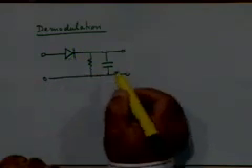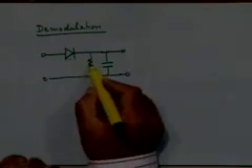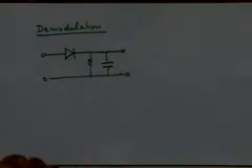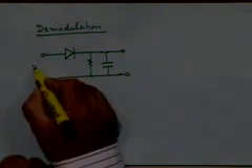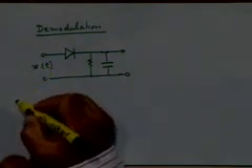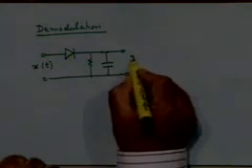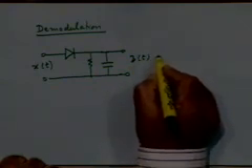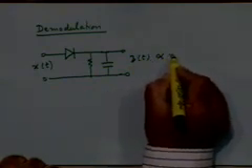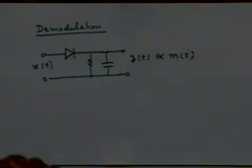We have a diode, we have a suitable value of the resistor here and a suitable value of the capacitor here. Input is a modulated waveform x(t) and output is, let's say, z(t), which is, we will soon see, proportional to the message signal m(t). Okay.